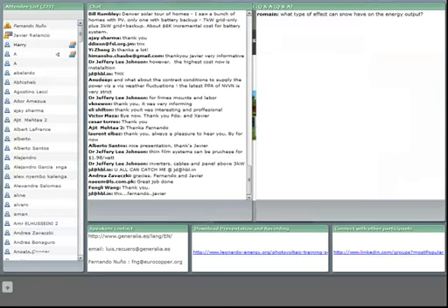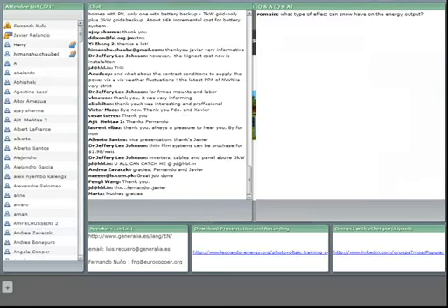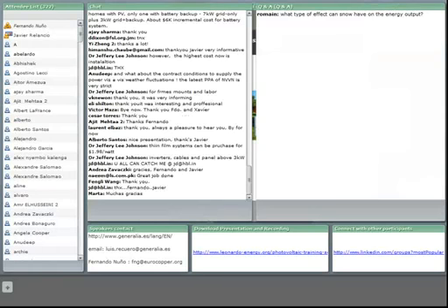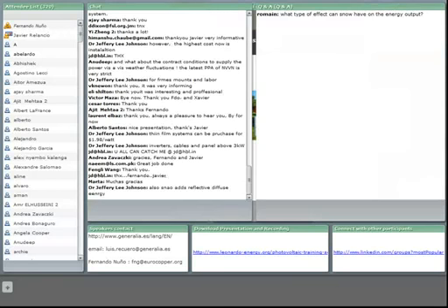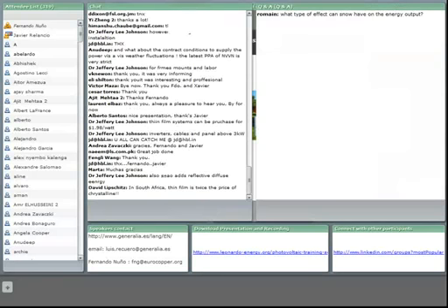As we saw during webinar 2, I think, the panel has losses because of the temperature. So if the weather conditions are colder, then we can expect more energy produced in a snowy area. But well, we have to consider that normally snowy areas have less sun, so we have to do the balance between these 2 points.